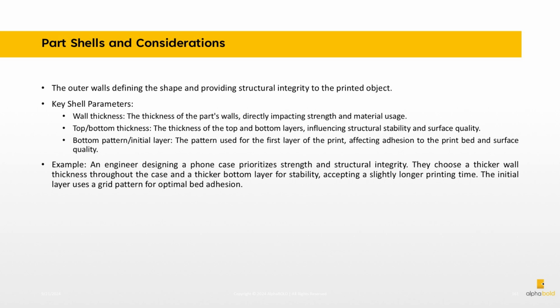Example. An engineer designing a phone case prioritizes strength and structural integrity. They choose a thicker wall thickness throughout the case and a thicker bottom layer for stability, accepting a slightly longer printing time. The initial layer uses a grid pattern for optimal bed adhesion.